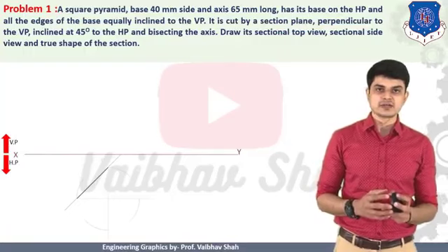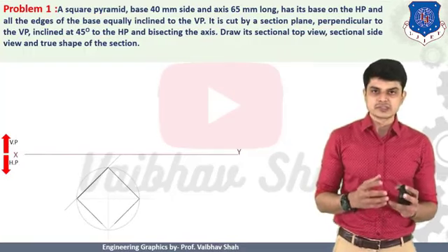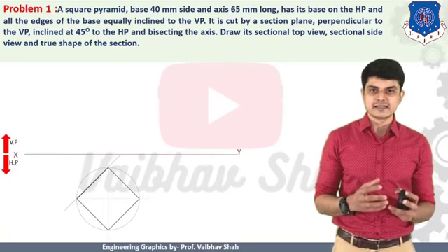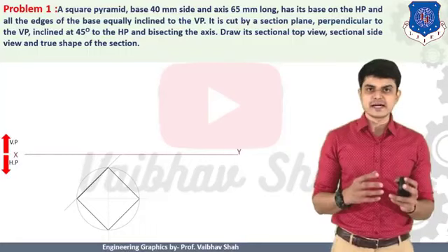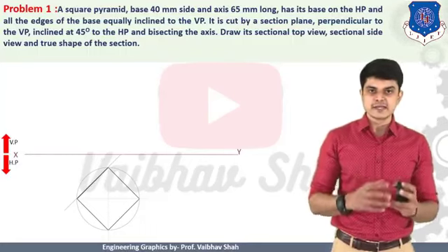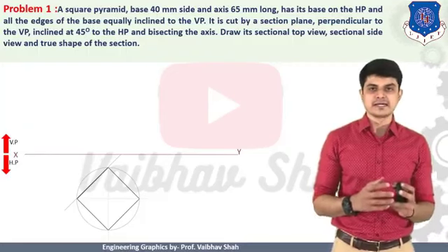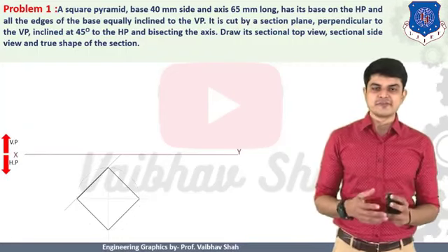So you will have one circle generated. After having this circle, you should draw your square by just extending the lines until you reach the circle's end point. So this is how we can generate our square which has all of its sides equally inclined to your vertical plane. Right? Thereafter let us draw the diagonal points of your square like this.